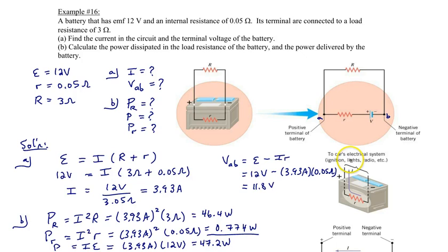And just a quick reflection, when you talk about old batteries versus new batteries, one of the big differences is that as time progresses, the internal resistance within the battery would go from, say, a few ohms to almost as much as 1,000 ohms over a long use. And it's also true if you think of batteries in the colder countries, like, say, Canada, in the cold mornings, a battery would basically provide less current, and that's because the internal resistance will increase with a colder temperature. So as the temperature outside drops, that internal resistance inside the battery will increase, and then that will provide less current from that battery.